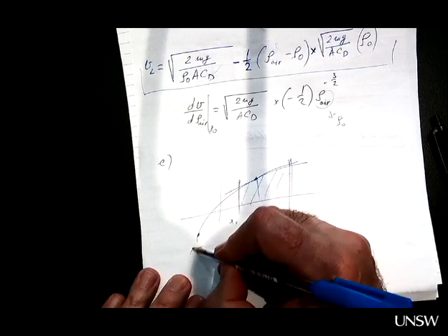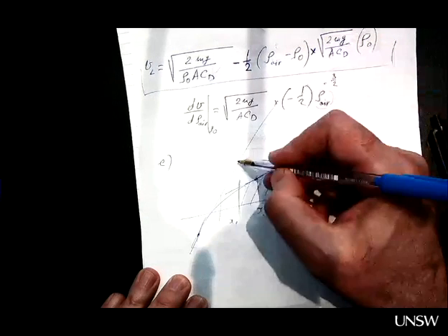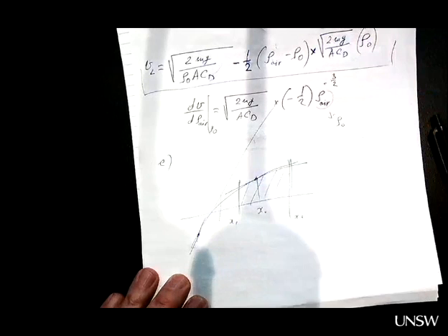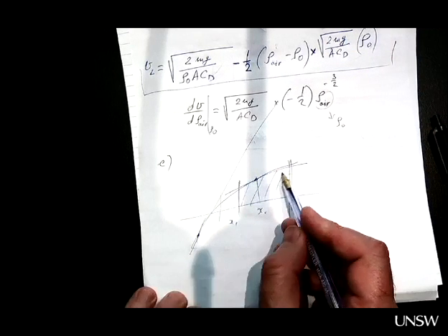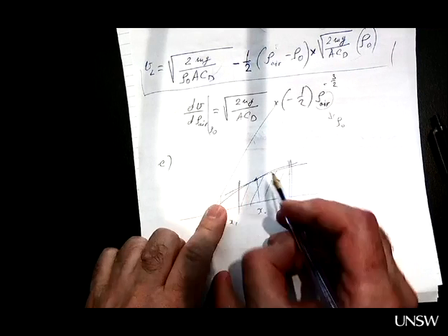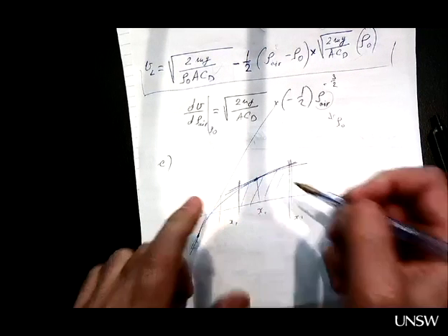Because when you draw a tangent here, your linearization error would be huge. So your linearization cannot be used as a substitution for the nonlinear expression, because this tangent does not describe your system. This tangent does, with a certain small error. So the selection of the operating point is an important thing. It should be within the operating range.